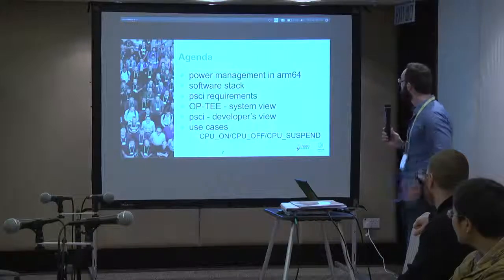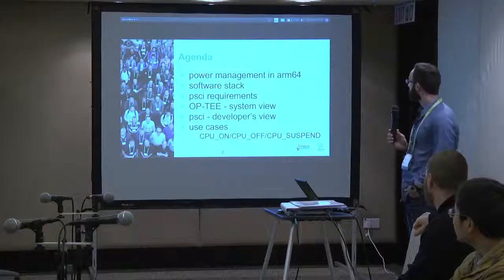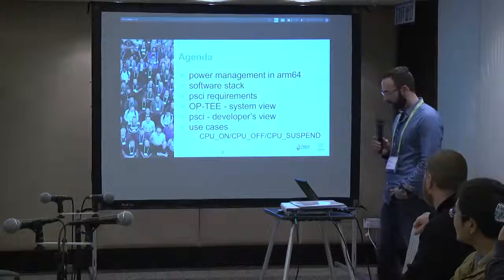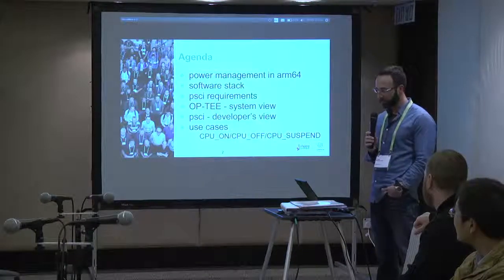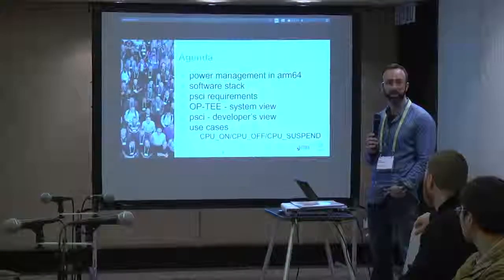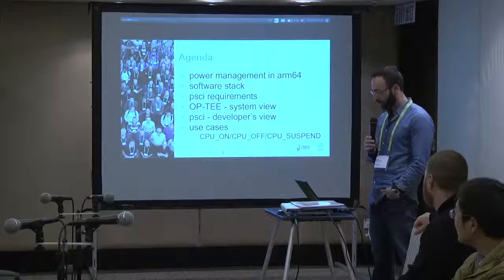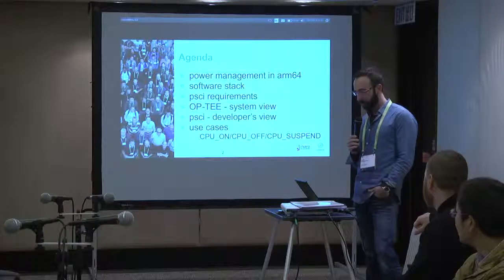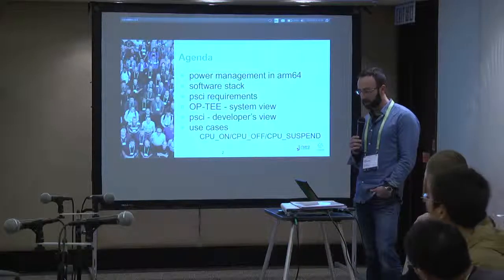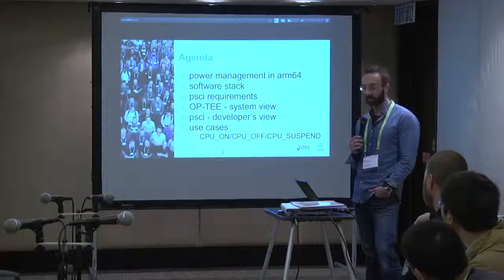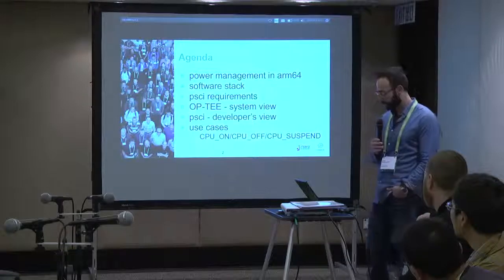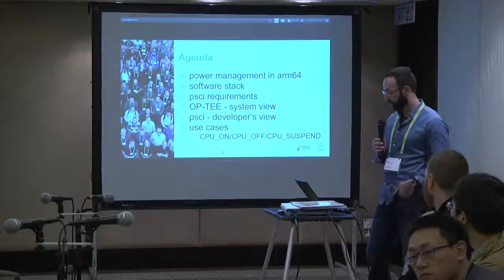So the agenda: a little bit explaining the reasons for the PSCI interface, defining the software stack, detailing the PSCI requirements, and something that has been in the specs for the last 2 years, since the spec was published. Then I'm going to present a system view of OP-TEE and a developer's view of PSCI, basically how we enter suspend states, how we hot plug CPUs, that sort of thing, and just go through some use cases.